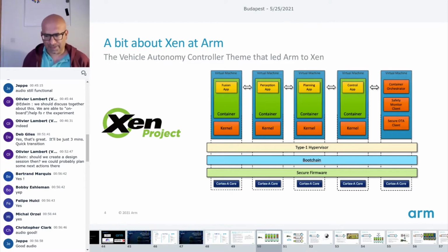And this graphic is just a hugely simplified example of what a typical implementation for vehicle autonomy control looks like, right? It's got a pipeline of software that consumes data coming from multiple sensors at the left end, so LiDAR, radar, camera, sonar, those kind of things. And it fuses all of that using industry standard algorithms and produces a nice standardized representation of the environment of the car, the immediate external environment. Then it tries to classify what it sees over there into people, road signs, tracks, whatever. And then it uses all of that information to calculate a trajectory, and then it turns that calculation into commands for velocity control, steering, that kind of stuff.